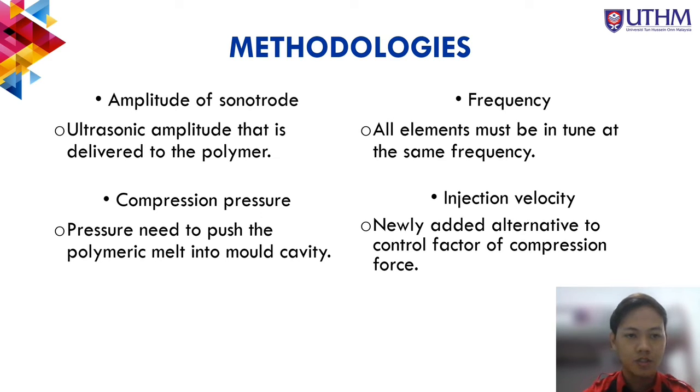Next is frequency. All elements must be in tune at the same frequency. In the recent case, very little information is known about the effect of the frequency in the ultrasonic molding process. However, we do know that the viscoelastic heating rate increases with frequency, but it only has minimal influence on the temperature of the polymer.